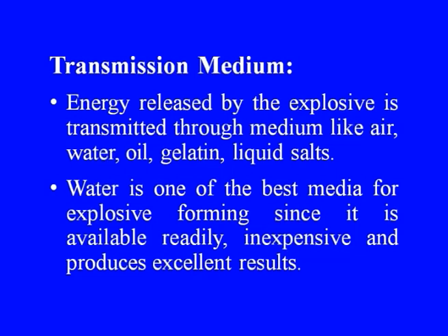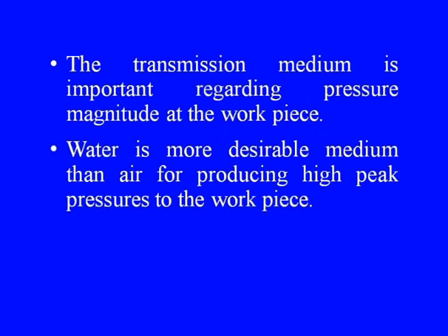Water is one of the best media for explosive forming, since it is available very readily, inexpensive, and produces excellent results. The transmission medium is important regarding the pressure magnitude at the workpiece. Water is more desirable medium than air for producing high peak pressures to the workpiece.